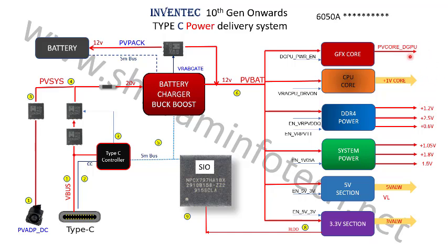This voltage is going to the graphics chip, this voltage is going to the CPU, this is the CPU core voltage, this voltage is going to the DDR4 RAM, this voltage is going again to the CPU, it's called the PCH voltage, this 5 volt is going to the amplifier and the VRM chips on the USB, and this 3 volt is going to the BIOS, then CPU, audio, networks, all these things, even the LCD also. So I have given the numbers here.